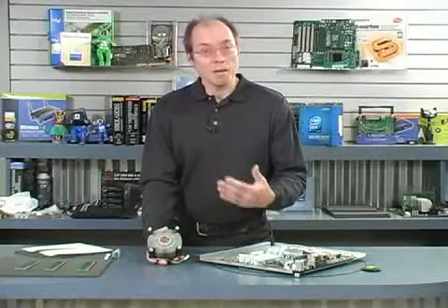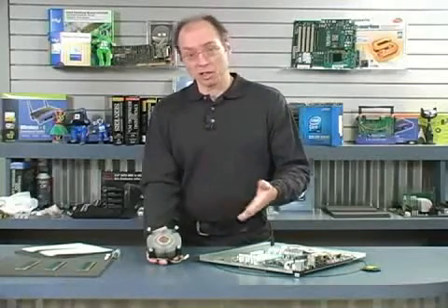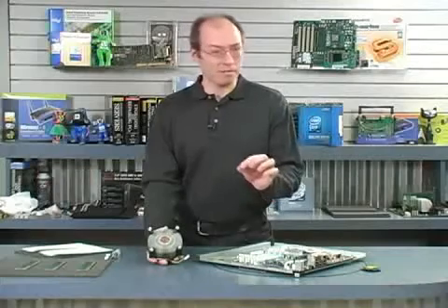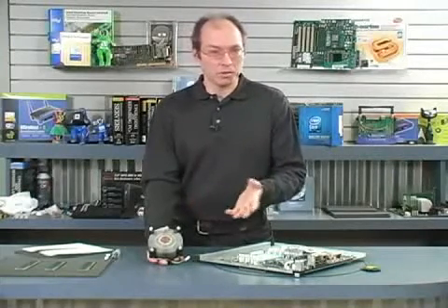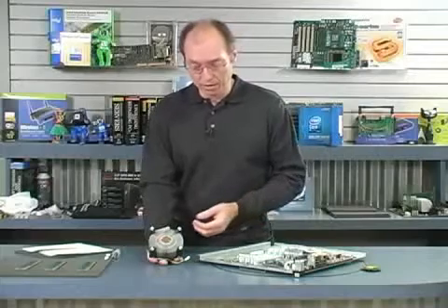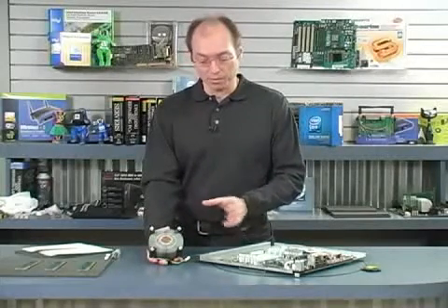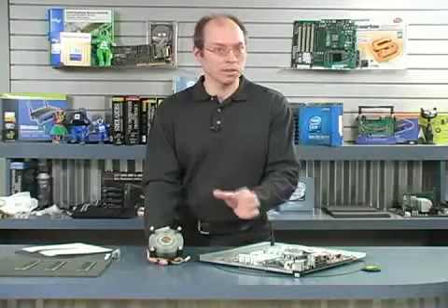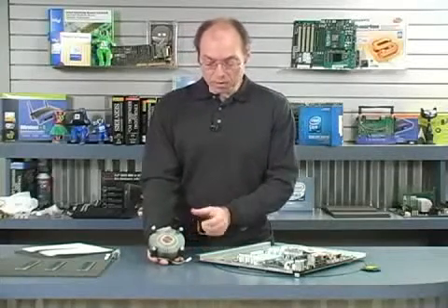Now, why the different materials? Well, copper is one of the best thermal conducting metals that there is. Silver is a little bit better than copper. It's like 5% better as a thermal conductor, but it costs 80 times more. So we don't usually see solid silver heat sinks. However, a solid copper heat sink would really be the best design. It would conduct the second most heat next to silver away from the processor.